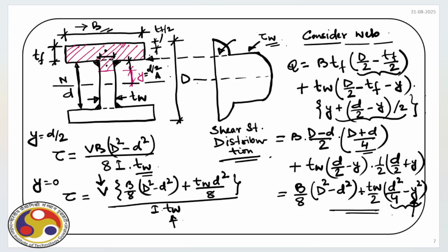But in our course, we are only worried about the shear stress distribution over the section, and we now have the shear stress distribution for a non-regular section. Earlier we had a rectangular section, and for that the value of the shear stress at the top and bottom is 0 and it is maximum at the middle.